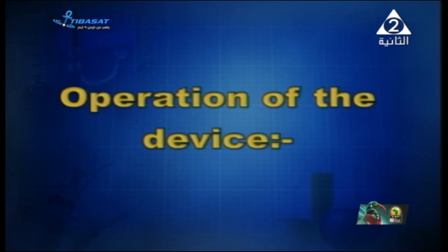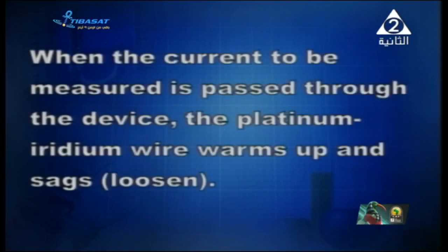And now talking about operation of the device, its mode of work. When the current to be measured is sent into the device, is passed through the device, the platinum iridium warms up, an amount of heat is generated and it expands, so it sags.